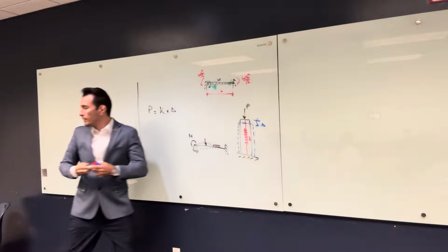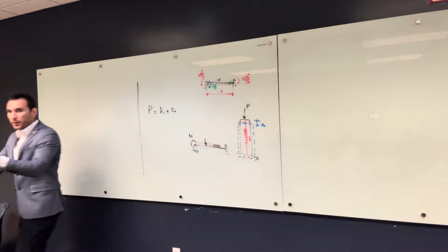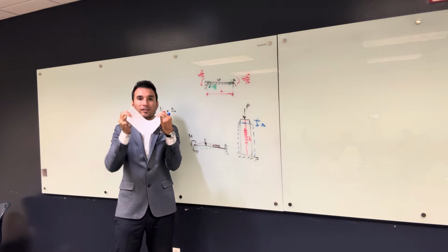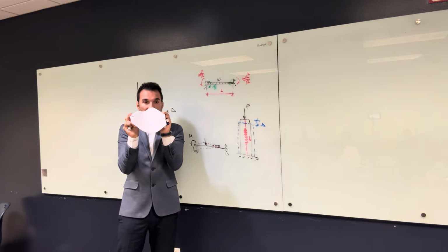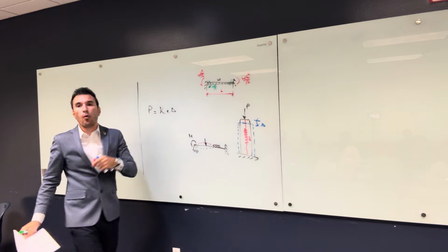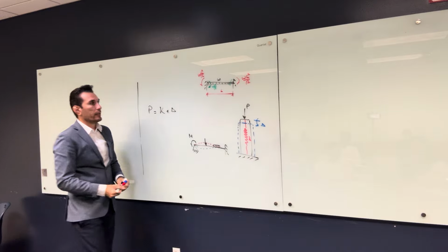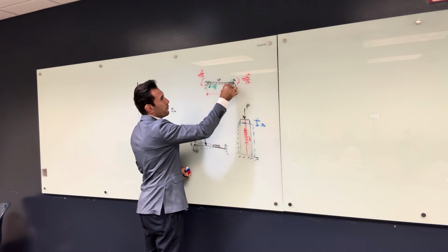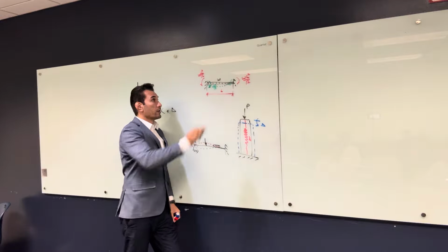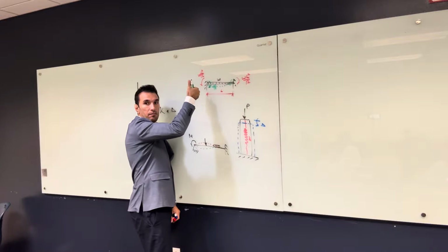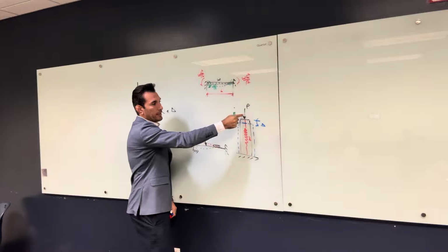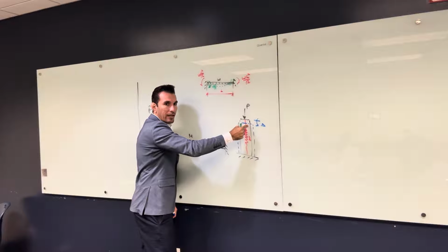So what happens is, this beam has a load, it wants to bend that way. So there is an action wanting to bend this beam, WL squared over 12, but the support makes a reaction, WL squared over 12, to resist this. But what is responsible for the deformation? Let's say you have a deformation, this is going to deform something like this. The action is the one that caused the deformation. So this one is the one that brings the beam down. That's the one that makes the deformation. And the external loads, also the one like this one, are the ones that make the deformation, not the reaction, right?